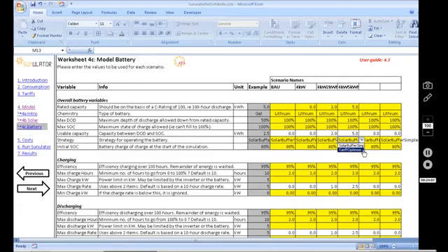On the other hand, if you pre-charge less than optimal from the grid, then you're going to maybe not have your battery charged up enough at the end of the day to supply your electricity consumption during your peak tariff times in the late afternoon, evening and night time. So yeah, if in doubt, just choose solar buffer simple.